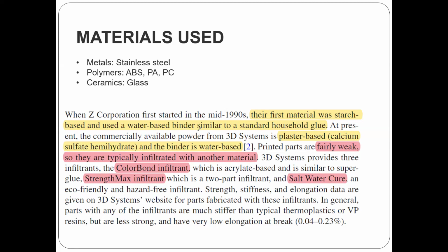Most of the time, students, infiltration is a process where you leave the printed part with another material, in a way that this new material will infiltrate, go inside and sit inside the material, and increase the density. It can overcome the porosity or the porous nature of the material, and it will improve the overall performance.